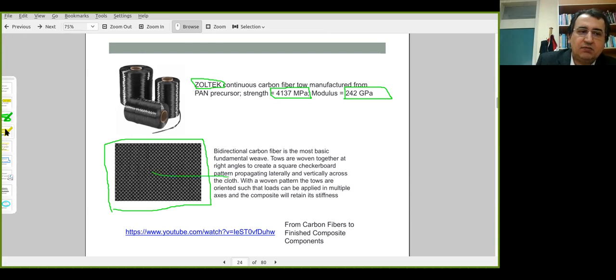High strength or modulus in this direction, high modulus in the perpendicular direction, and in all directions in between, you'll be able to compute high modulus of elasticity. But as an engineer, your task is to quantify this distribution. What is the modulus of elasticity in this direction? You need to use the underlying theory for such lamina or plates to determine such material properties in arbitrary directions.